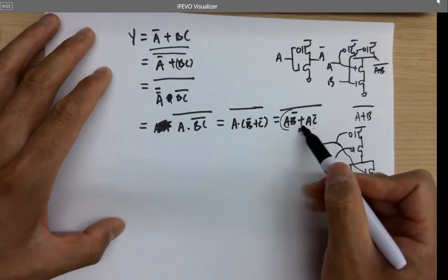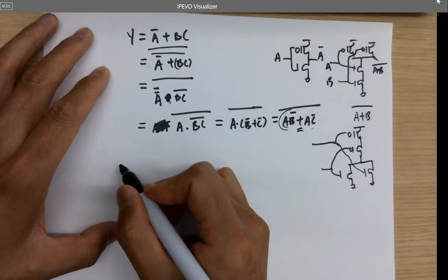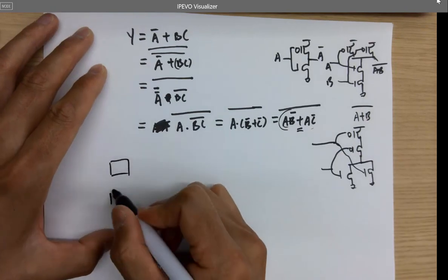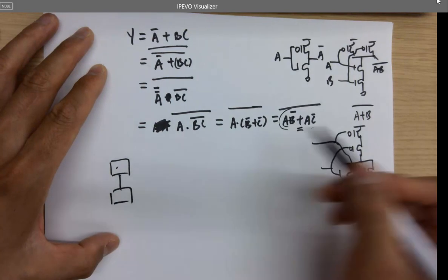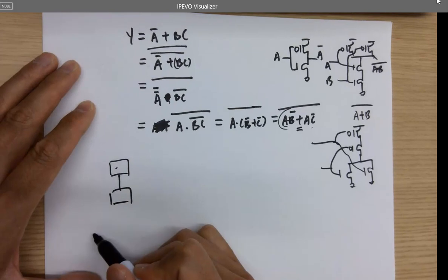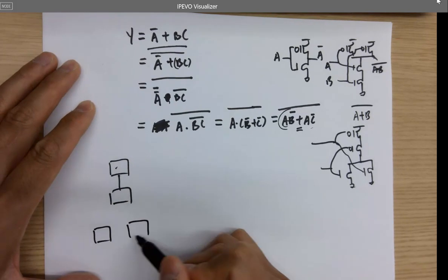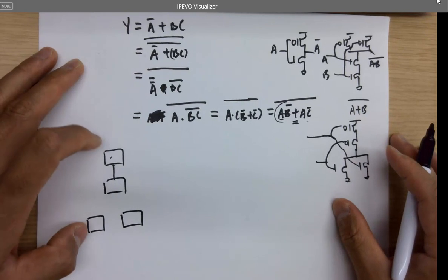It's OR logic, right? It's NOR. Yeah, if you in series. So you have one box here, one box here. These boxes are these guys, but you don't worry about that right now. But they should be in series, right? And then you got two boxes at the bottom for the NMOS in parallel. That's a NOR gate. That's a NOR logic.